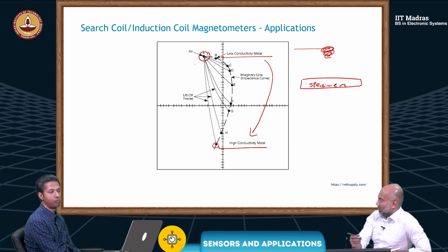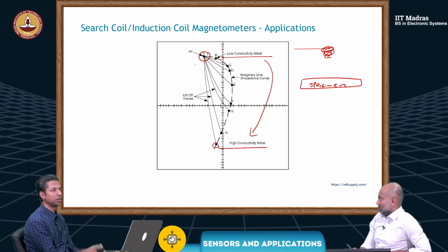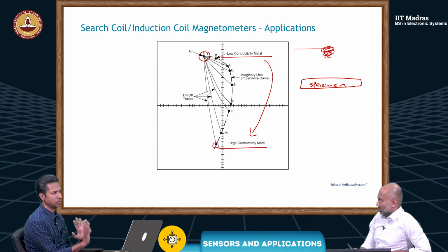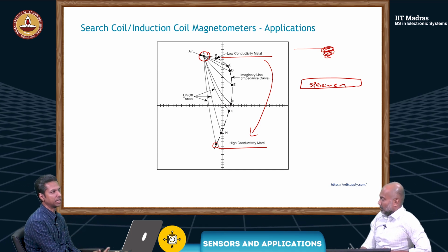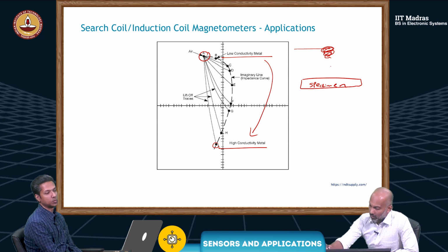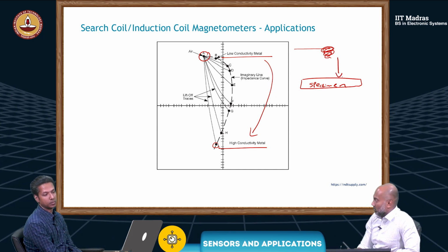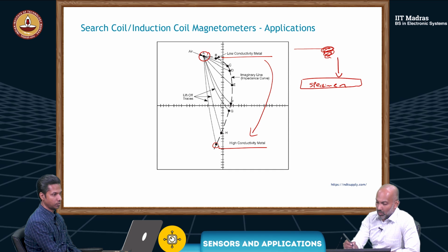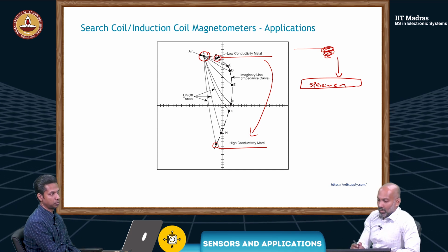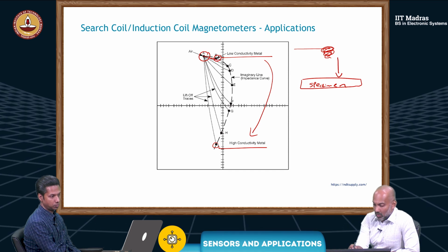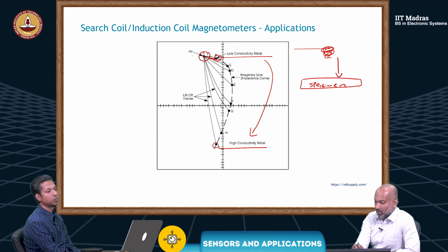You measure that impedance, the impedance of the coil, with no influence due to the object. Now you bring the coil close to the specimen and measure the first material, which is B. This liftoff trace is the change from that initial impedance to this point.